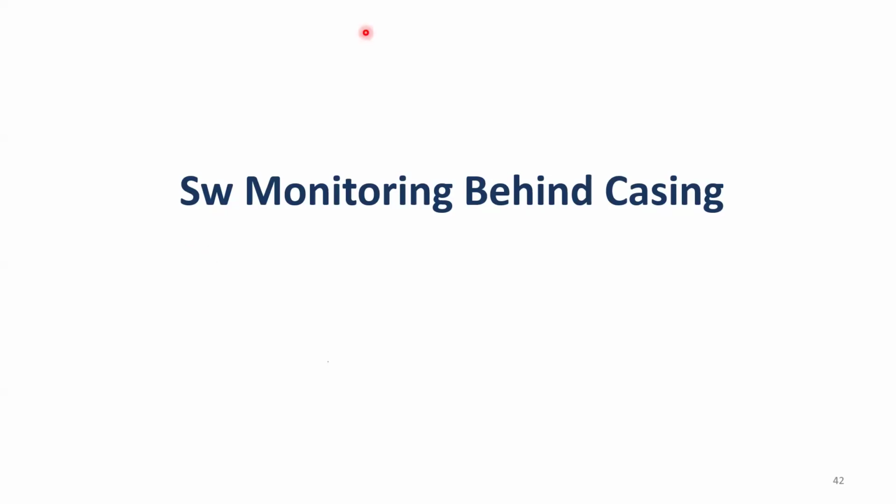Okay. Hello, I have some questions. Suppose one well has an SRP or ESP, and the flowing pressure will not be sufficient. It will be able to produce in those scenarios. Suppose we start getting some water, or some thick zones, or cross flow, or something happens. Then how will we find out which zone is contributing how much? Because there will be a pump. If we remove the pump, there will be no flow from the well. So in those scenarios, can we do some kind of production logging?